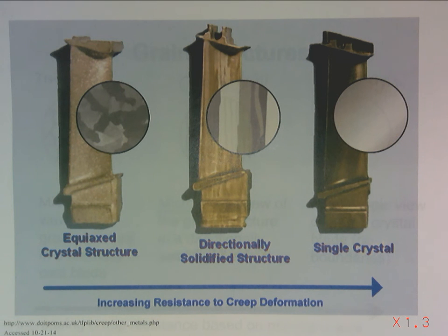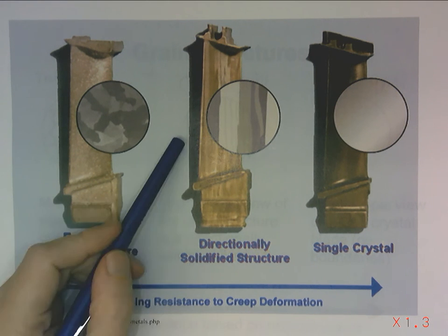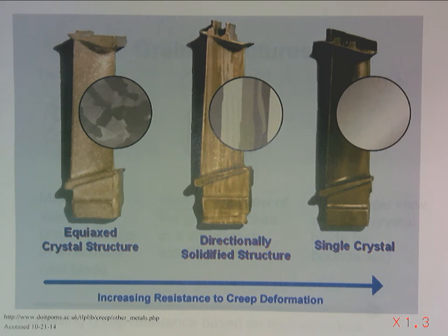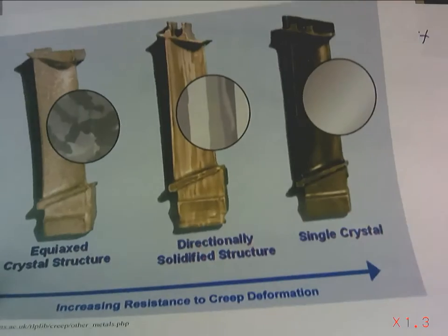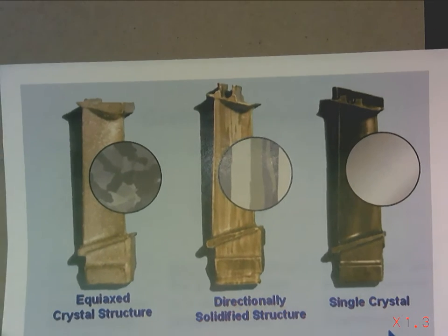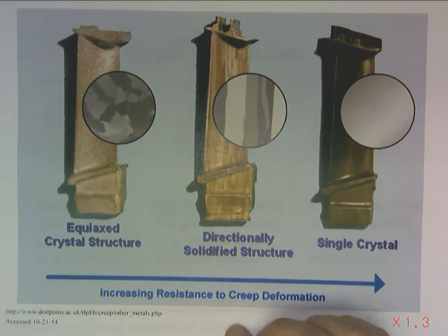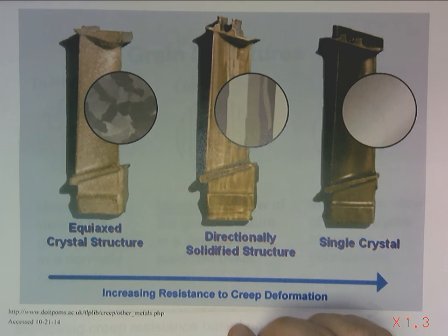Sometimes maybe we can take an engine and run it at a lower temperature. We can add better cooling. So we can add fancier versions of radiators or better airflow through a turbine engine or something. Usually we're looking at changing the material either microstructurally or chemically to resist the creep failure, though. Okay, so we have now survived creep failures. And yeah, I think that's it.